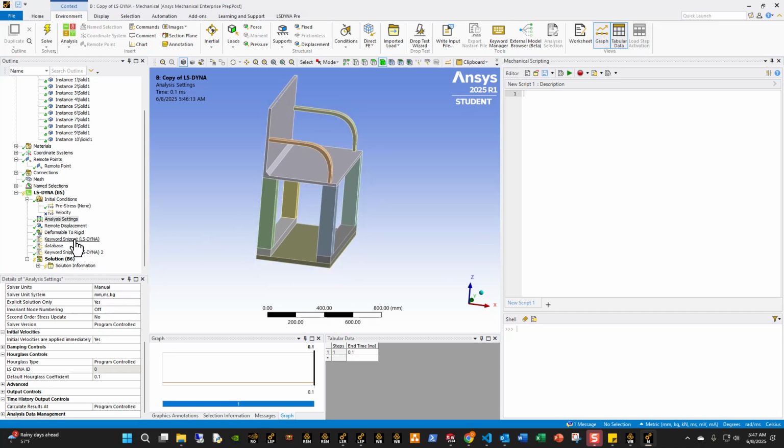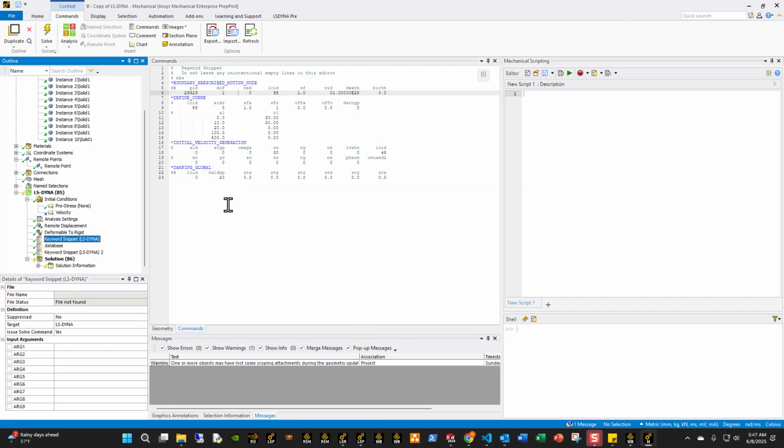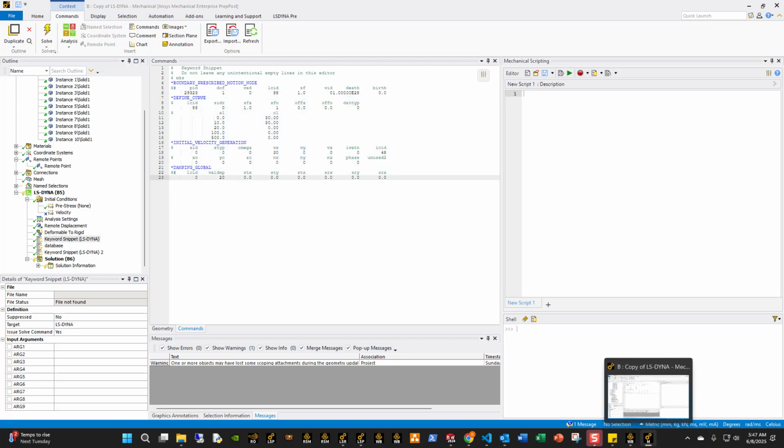That's the first thing. Second thing here is that I want to generate almost like a triangular acceleration to get it to a sudden stop. And so this is what I've done here. The global damping here, I'm just going to use a very small number because of the nature of the dummy that exists.